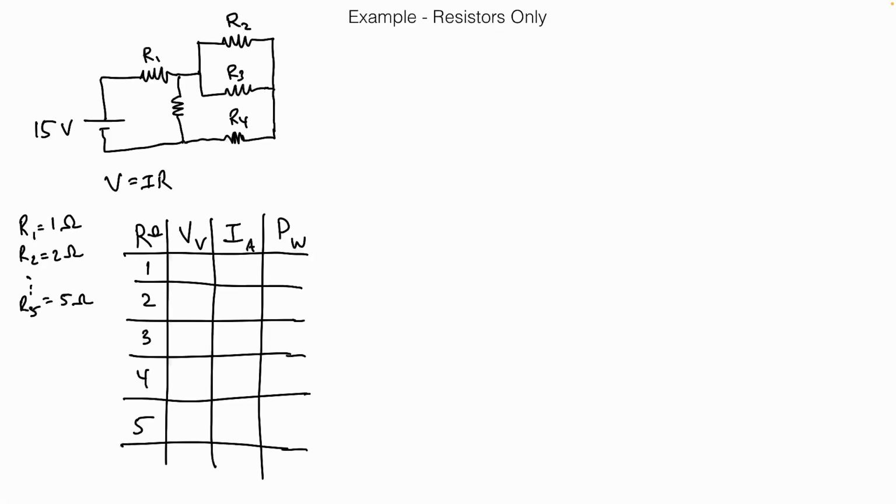It looks like 2, 3, and 4 are parallel with each other, doesn't it? Just because of kind of how they're drawn in the thing. But could I have drawn R4 right here instead? Sure. There's no difference schematically between the connections. I draw it that way. So don't rely on the actual physical location. Look at the junctions. Look at what is happening to the wires.